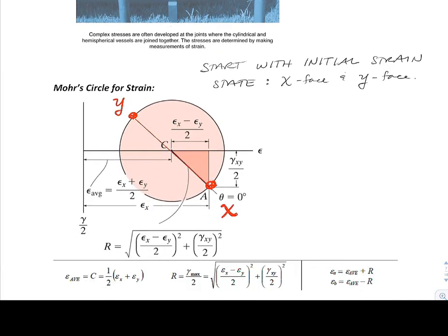And so here's the exact look that we've got for Mohr circle. Again, we're just going to plot 2 initial axes. This is going to give us 2 points. We'll be able to come up with the center of the circle, the radius of the circle, and then we'll be able to rotate through any angle theta that we might be interested in. Here we'd end up with epsilon max, epsilon minimum. We hold off on doing the 1, 2, 3 until we know what's going on with epsilon zz, what its value is.